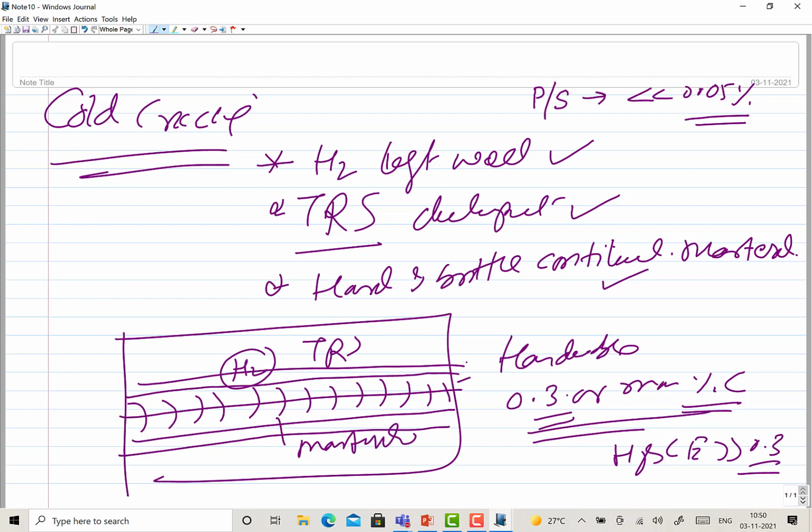So invariably, in welding of hardenable steels, you have the hydrogen if improper welding is carried out without taking proper care of the moisture or the organic compounds like oil, paint, etc. from the surface of the base metal.